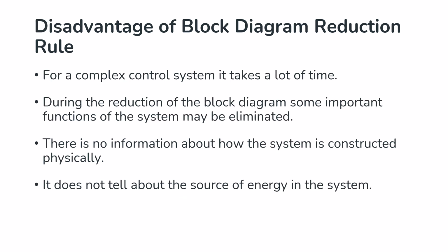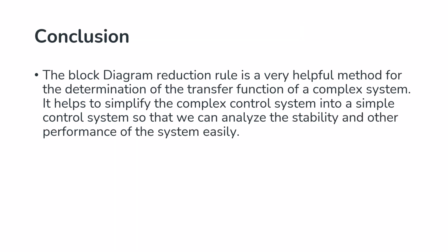Now, the disadvantages are: for a complex control system, it takes a lot of time. During reduction of the block diagram, some important functions of the system may be eliminated. There is no information about how the system is constructed physically. It does not tell about the source of energy in the system. These are the advantages and disadvantages of the block reduction method.